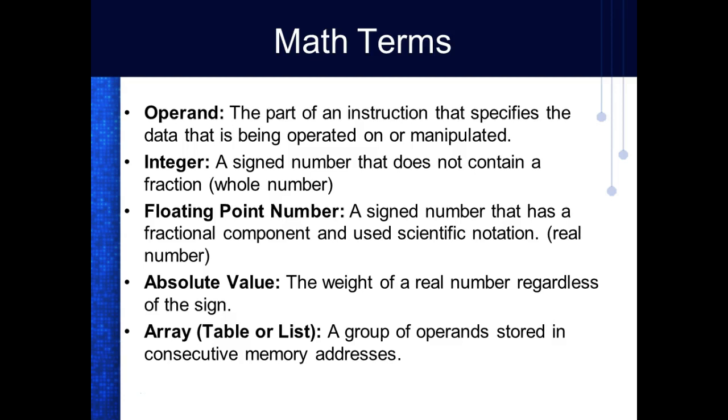We call them overflows. So we have a bit inside our status register or inside our flag register that indicates when you exceed the range. So on an up counter, we have an overflow flag. On a down counter, we have an underflow flag, right? The counter will keep counting, but what happened is you just screwed up. You've lost the sign,